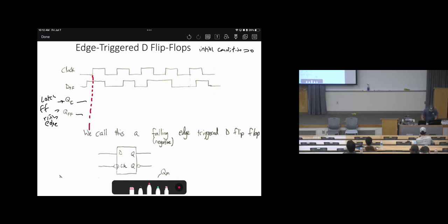So let me do the flip-flop first, because the flip-flop is much easier than the latch. In the flip-flop, it's rising edge. Rising edge happens here, here, here, here, here. So only at these 5 arrows will there be updates. The rest will hold.